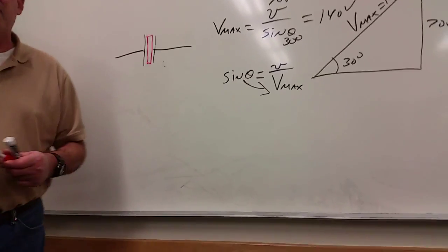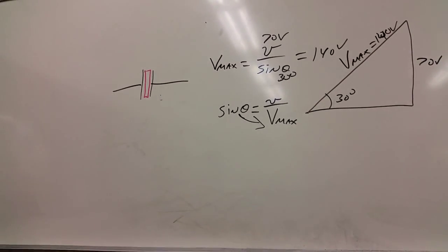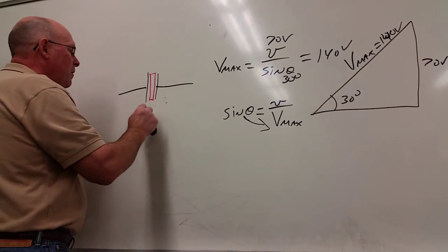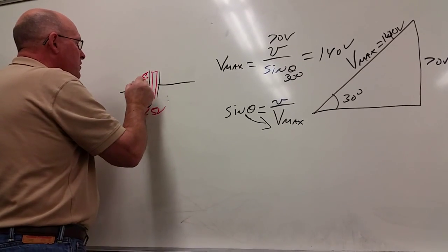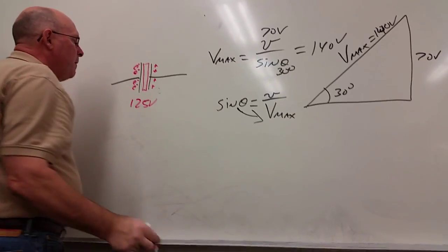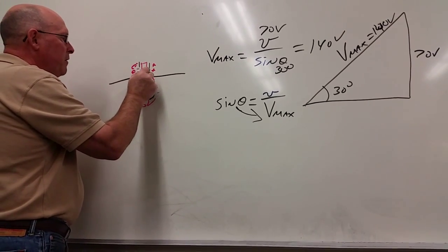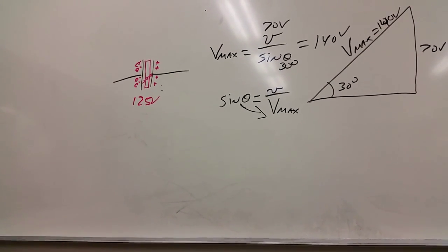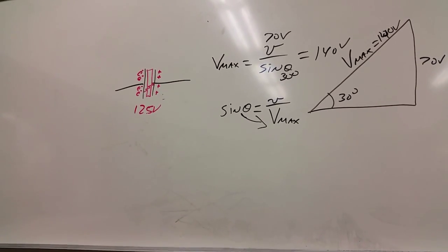Okay. I've got a capacitor here with a dielectric in it. And it tells me it has a breakdown voltage of 125 volts. And so at 125 volts, if I have electrons on this side, negative ones, and positive over here, the electrons are going to find their way through this and it will actually pop like a firecracker and ruin it.